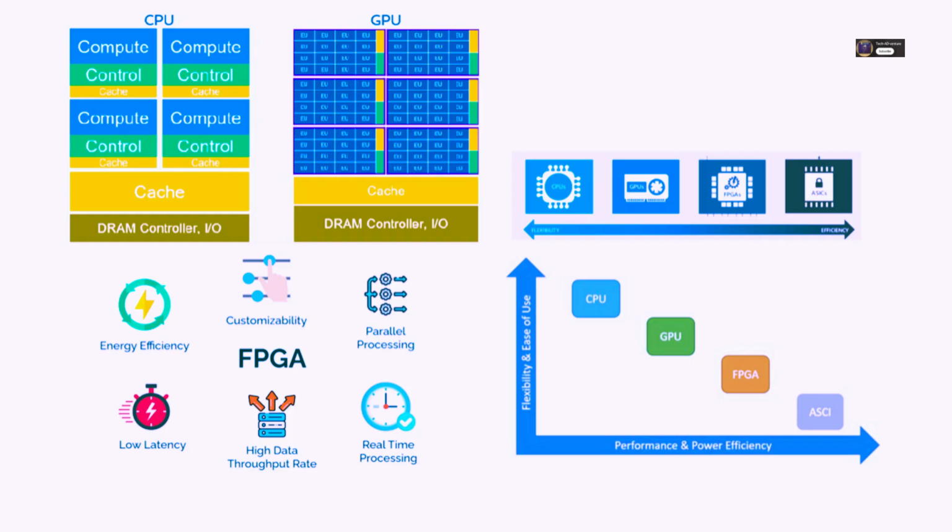Exactly. FPGAs allow for rapid iteration. Test the design, find bugs, fix the logic, reprogram it, maybe in hours or days. You don't have to wait a year and spend millions for a new silicon spin like you would with an ASIC revision. Okay. So you use the FPGA to prove out the concept, stabilize the design, make sure the standard works. Then, once everything is locked down, validated, and ready for mass deployment, you commit the resources to create the highly efficient fixed-function ASIC for the commercial rollout. The FPGA de-risks the massive ASIC investment.